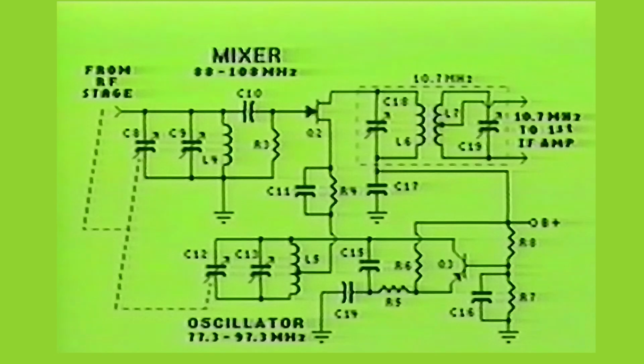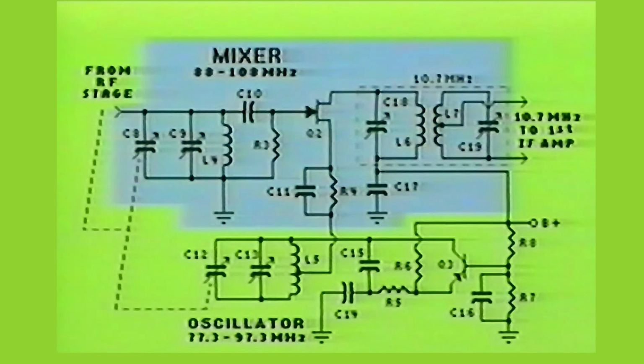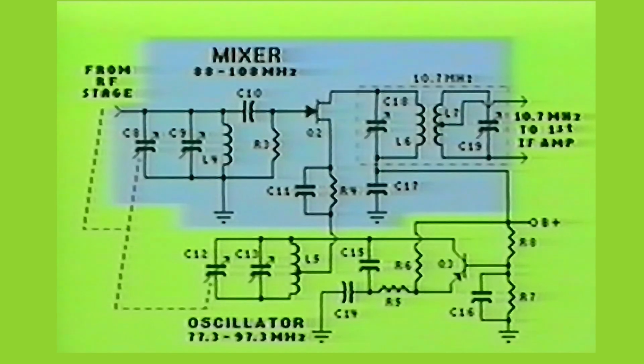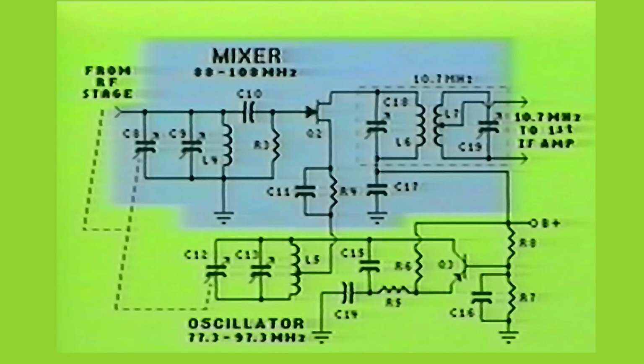Here you see a two-stage mixer oscillator circuit from an FM receiver. Notice that the mixer stage contains two tuned circuits and a junction field effect transistor. You may have also noticed that the tank circuit at the output is contained in a shielded can to eliminate stray voltages which would affect the operation of the circuit.